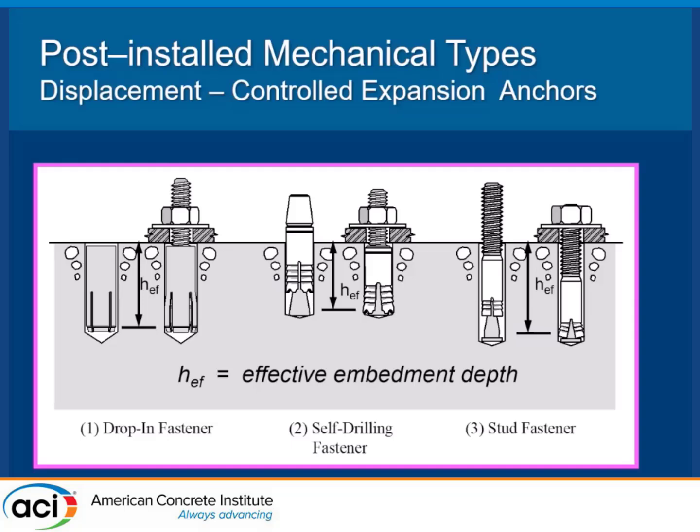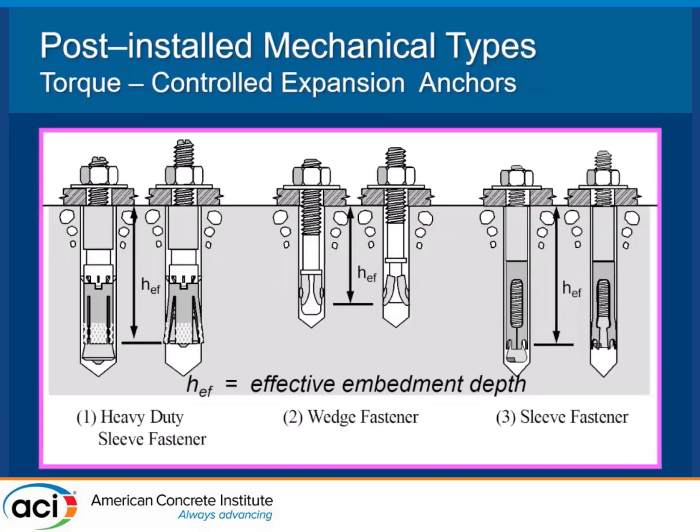cracking is something we need to consider and understand. And there's a fundamental shift in how we treat anchorages in concrete, and we'll get into that in the history in a second. But understand, if you're using a displacement type expansion anchor, once you put it in, there's no further adjustment. And so if cracking becomes a big issue on your structure or your application, you're going to lose your strength very, very quick in this type of post-install anchor.